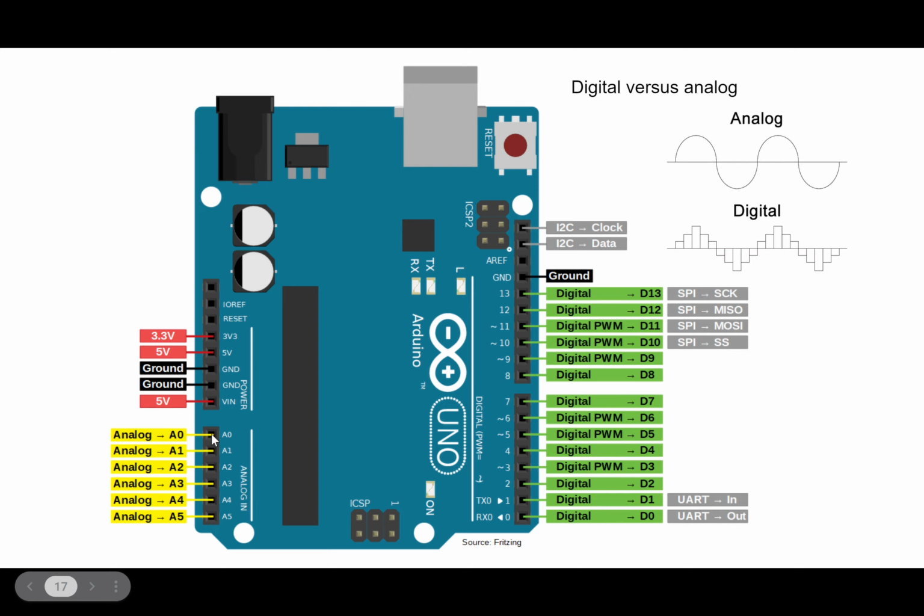So these analog pins, you will usually program them to either be an input or an output. That'll make more sense as you see the code, but this is for either measuring something that can be of varying voltage or an output that is of varying different voltage. It's not just going to be on or off. So you have 6 of those.